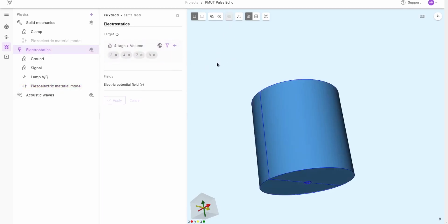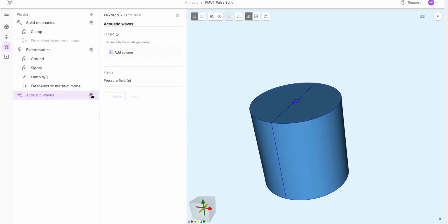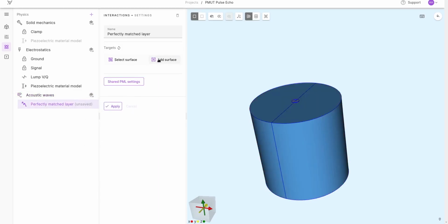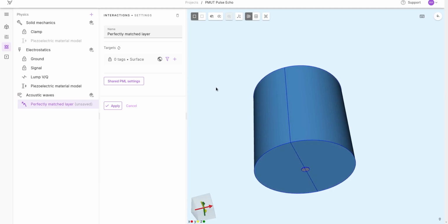For that, two things we need to do is first select the regions where this applies. So it's the water. That's where the physics is defined. And then we want to say that there is two things. So perfectly matched layer. So as we said, we have some extension of silicon on top and bottom. So this will lead to wave reflection.